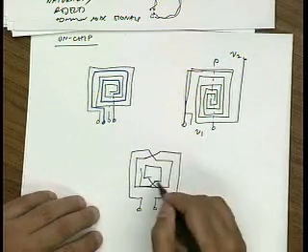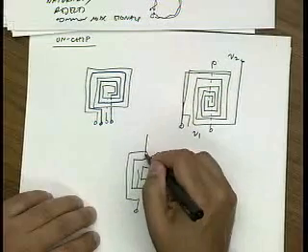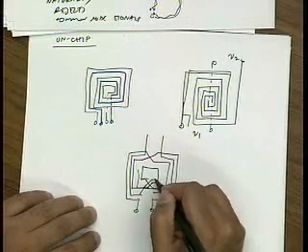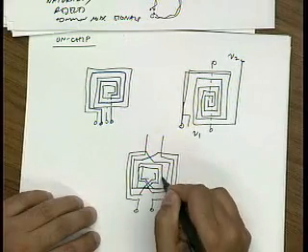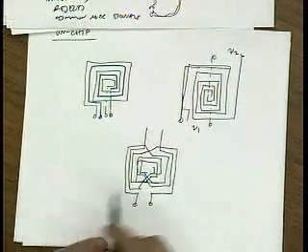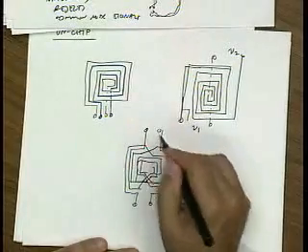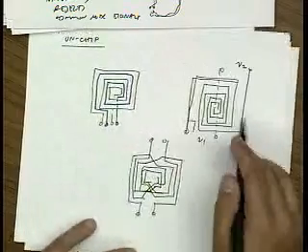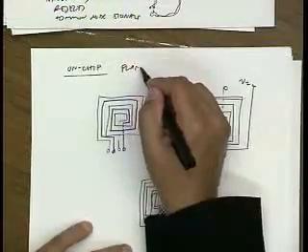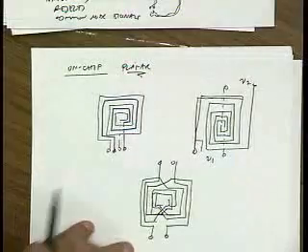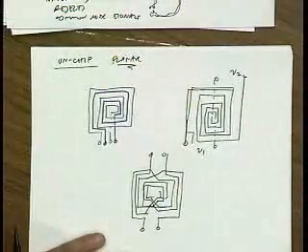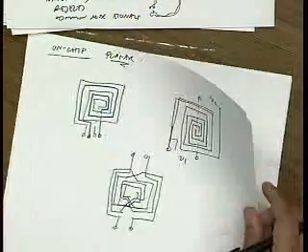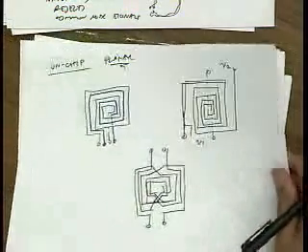So this is a symmetric winding. I can do another winding that effectively does the same thing. A little bit hard to see, and I actually mucked it up. So anyhow, you could build a symmetric version of these transformers. But these are planar structures on chip. They have to be planar for the most part. If you have multiple metal layers, you can actually build non-planar inductors and transformers. We could talk about that more, but it's a little bit off course. So let's get back on course.